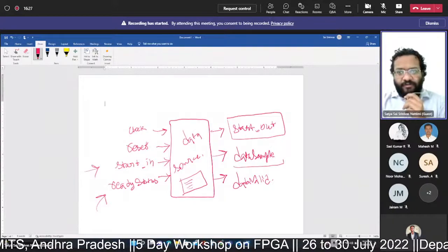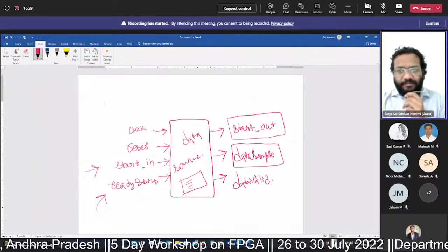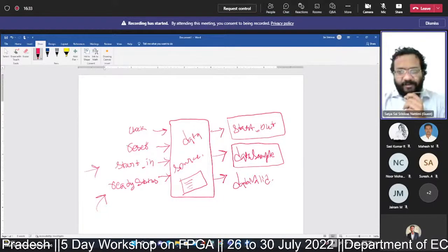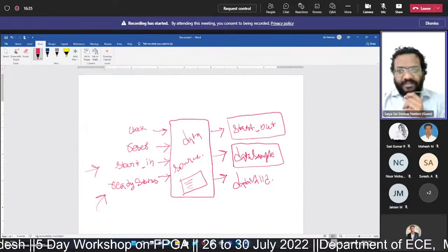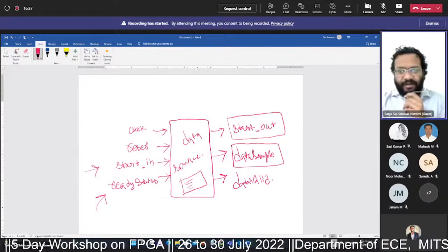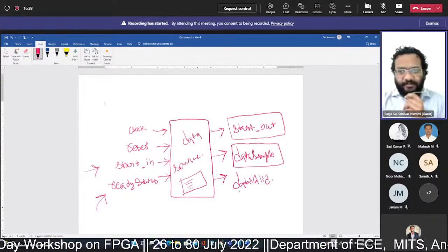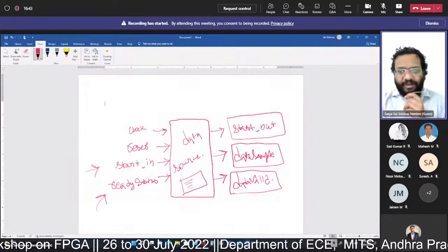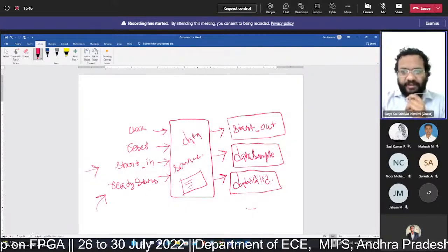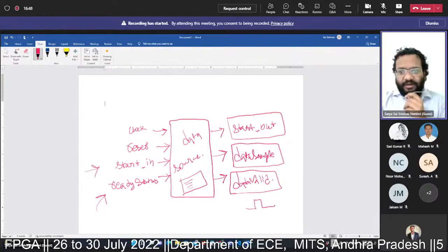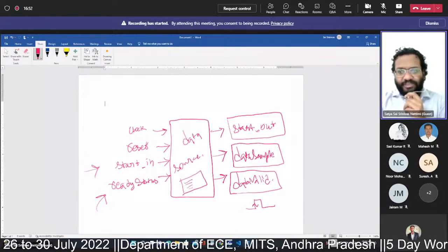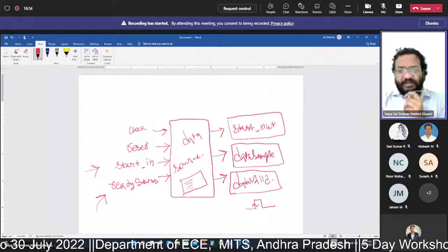The data source provides the signal samples via the data sample input, and whenever it provides a sample, it acknowledges with a data valid signal, a small pulse of duration equal to one clock cycle.